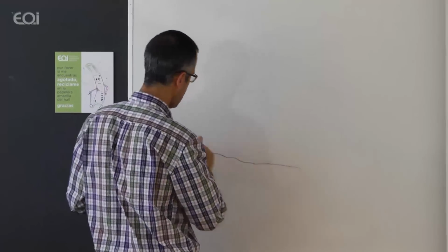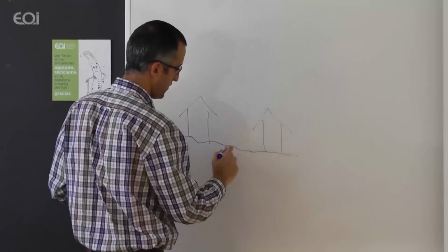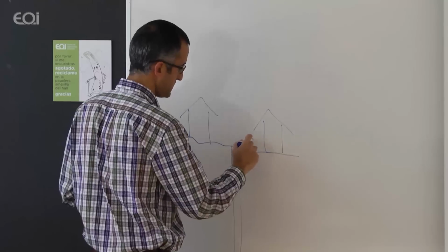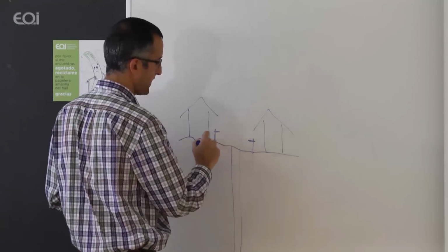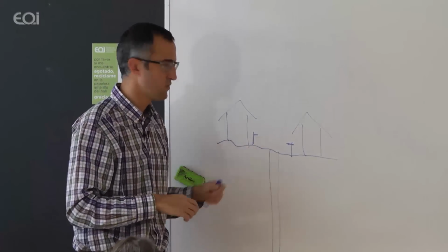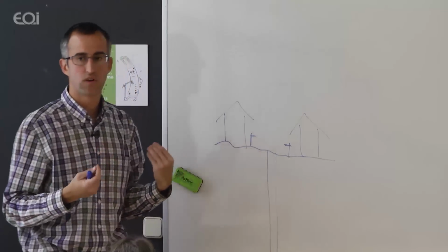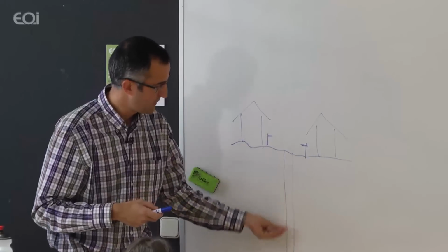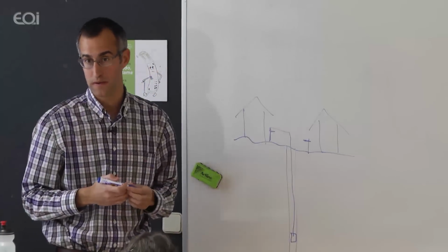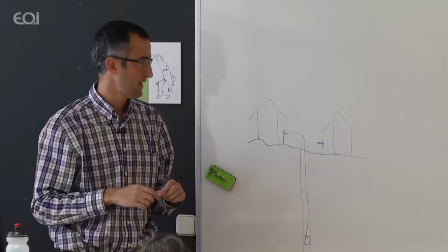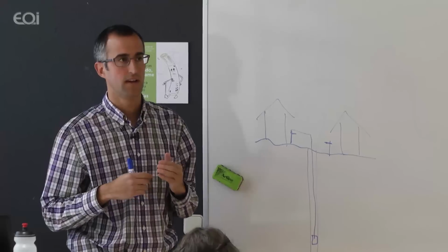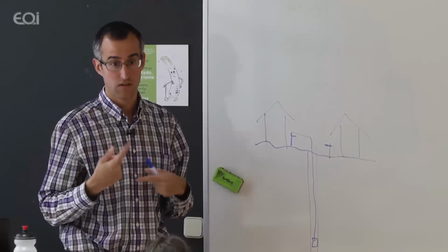So the houses were here, and the borehole that we did was here. And we installed some water points in the village. Imagine that a child goes to this water point and wants to have water. It's impossible to have water all the time only using a pumping system, because we would have to use the pump maybe 100 times in a day, and that's not very good for the pump. It's better to use it maybe 5 times in a day, because if not, it's working, not working, and it's not very good for the machine, right?